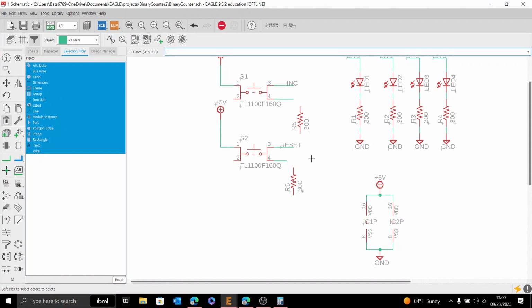Going back to your resistor divider, current takes the path of least resistance. So we'll make this something large, like I think I did 3.3K there. Good enough, considering that we have no resistor going that way. It's called a pull down because it's pulled down to ground. If you had it going to the source, that's a pull up. So one more time, for a pull up, the default value is high, for a pull down, the default value is 0, and your switch should swap that. Good? Okay.